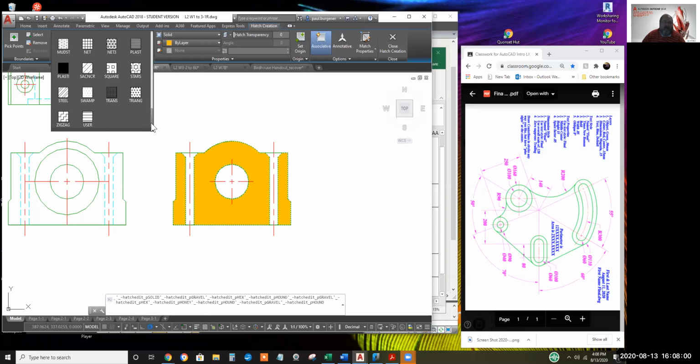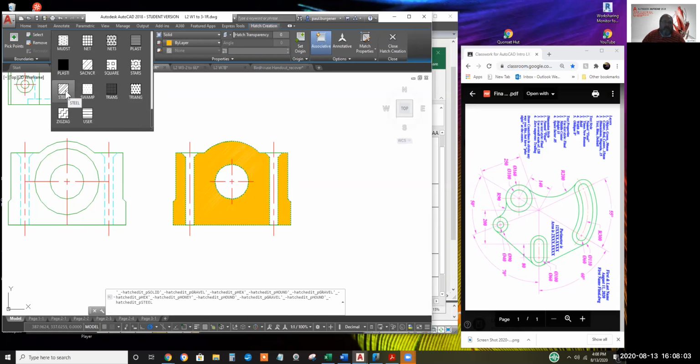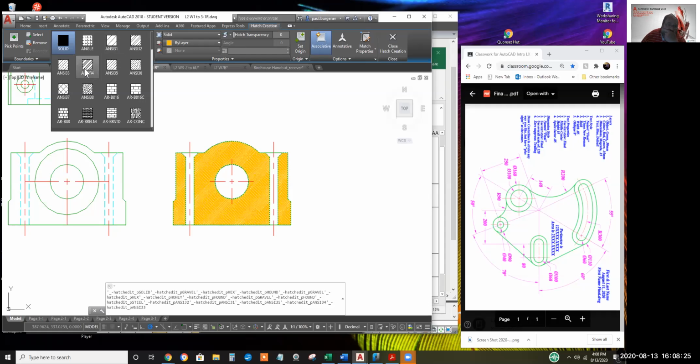The crosshatch patterns for the materials, for the metals, steel. I think there's one for aluminum, or aluminium, as they say in Britain. I think ANSI 32 is aluminum. ANSI 31 is steel. No, that's cast iron. I don't know what these others are. But these ones that are for a specific metal or material, how to put this, these squares are very small squares.